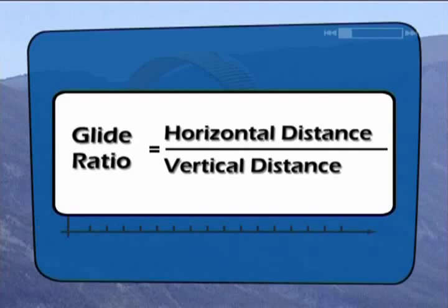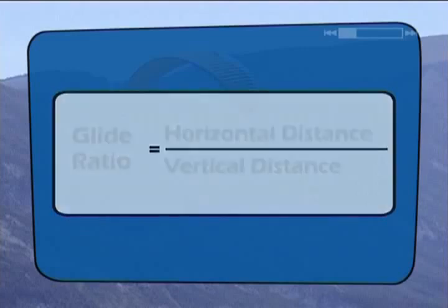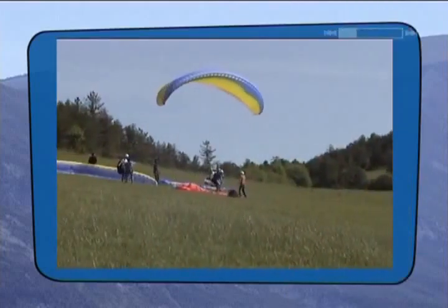This is called your lift-to-drag ratio. It's a technical specification of your wing. The lift-to-drag ratio doesn't change unless the wing is damaged. We'll see later on in the flight chapter that the wind or micrometeorology can influence the trajectory. The distance covered will vary, and in this case we'd refer to its glide ratio.